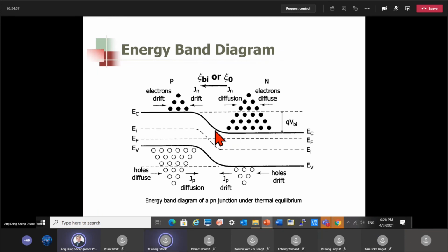Then now the question becomes how the conduction band energy changes, and the valence band energy. Remember earlier on, I answered a question on the energy band diagram being an inverted potential diagram. So you must remember this. Secondly, the change in the EC. So this EC is higher, this EC is lower. This difference is caused by charge transfer.